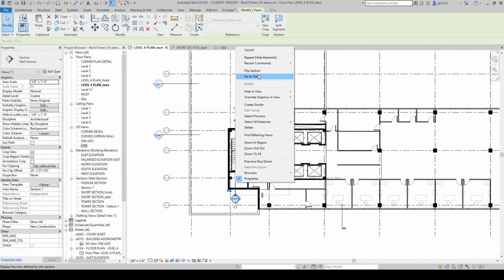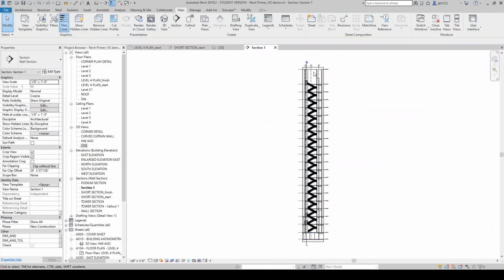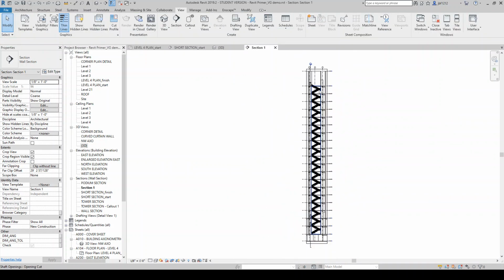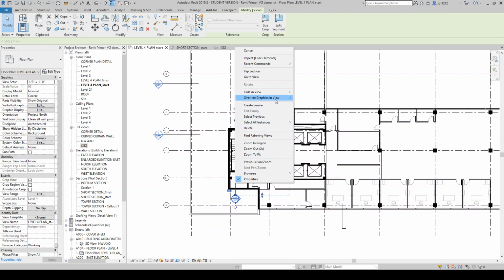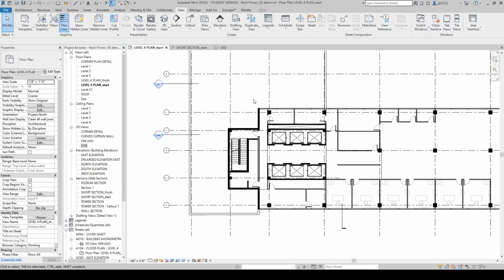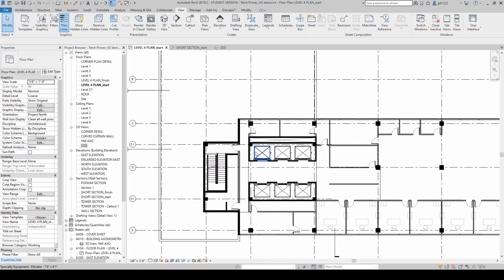This was more of a process section that we used so that we could make this multi-story stair object here. Now, as we're setting up our plan, this is not a section that we want in our drawing set. We can come here and hide that section view. So that would be a good use for that.